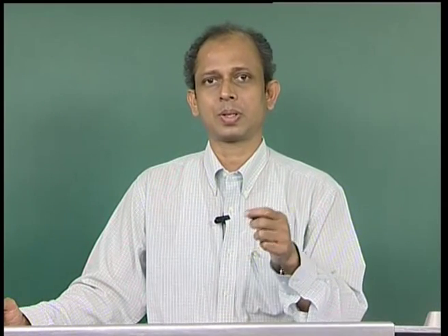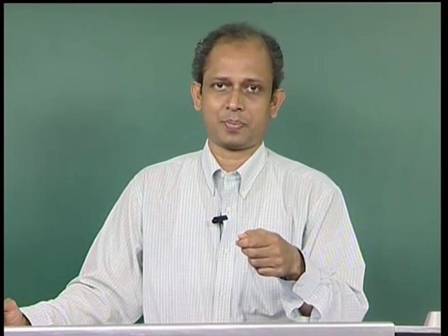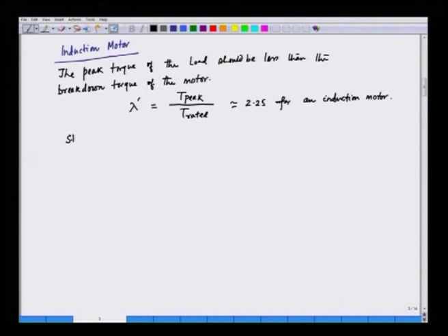So, after we have obtained this rated torque, we apply this condition, and the condition is that the peak torque by the rated torque should be less than lambda prime. So, we can note down the various steps. Step 1 here, select the rated torque based on T equivalent calculated.